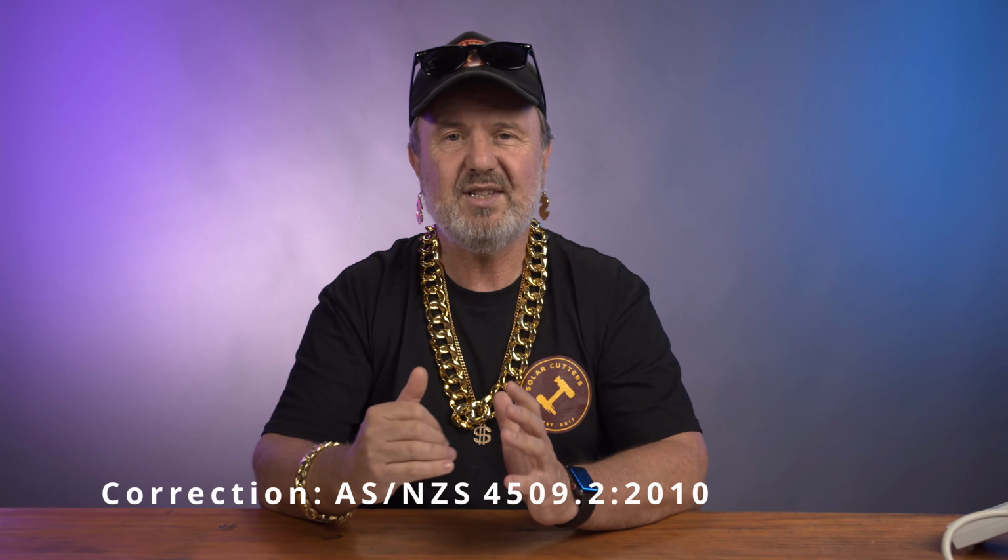How do we know what's the right size? Now, this is once again a budget question, but a reasonable approach, and this is following the principles of our design standard for standalone power systems, AS/NZS 5139, which says that you should consider coincidental loads. Now that means things that come on at the same time, and it can be with discussion with the customer what's a reasonable expectation. So for instance, some appliances are almost always synchronized. If you have a water pressure pump and you use any appliance that uses water, like a dishwasher or a clothes washer, the chances are they'll both be on at the same time.